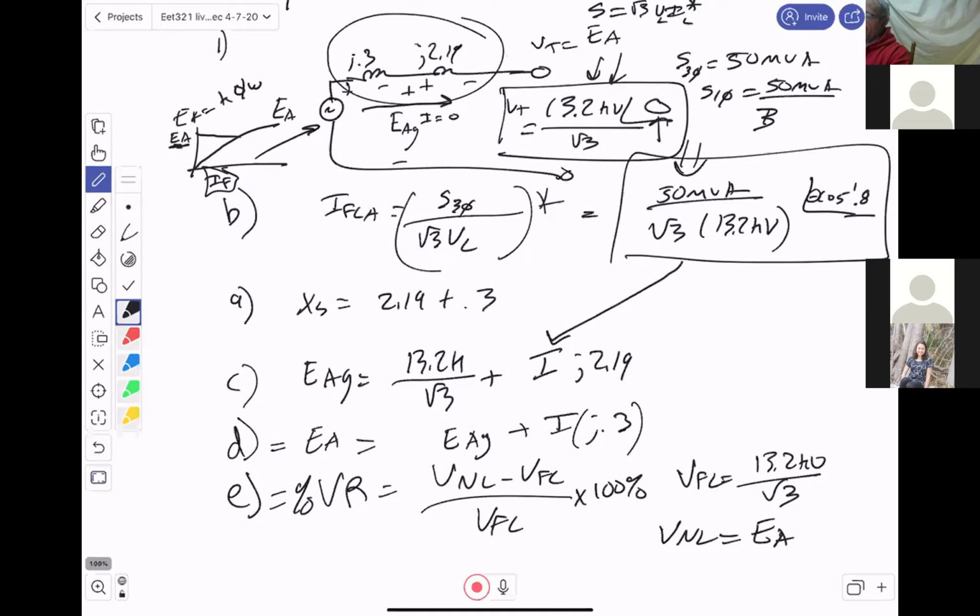The power, though, remember, is a function of the torque angle, and that's when you have to increase or decrease the torque angle, which means you have to slightly speed up or slightly slow down the generator for a brief instance in time. That means you have to increase or decrease the amount of steam or fuel that goes into your reciprocating engine to get it to speed up or slow down for a period of time. So I said that that was E, that should actually be F. So let's make that F.